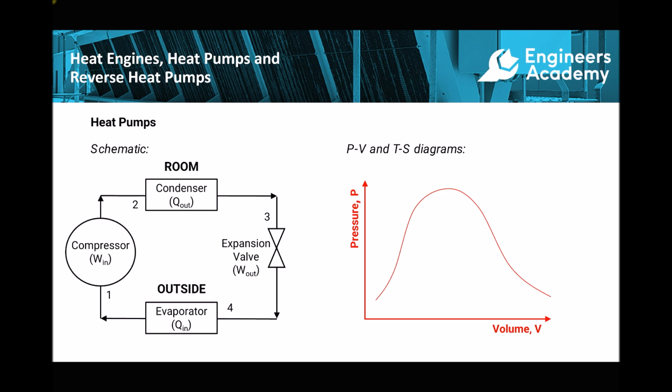So one difference we observe here is that we have a compressor instead of a pump. And the reason we have a compressor is because when the refrigerant passes through that component, it's already a gas. Moving from 1 to 2 then, we have a dry saturated fluid entering the compressor, and exiting the compressor, we have a superheated fluid at a higher pressure. When we compress the gas, its volume decreases and its pressure increases. As we'll see in a moment, this is also an isentropic process. So we have an ideal compression in order to increase the pressure and reduce the volume of our gas.